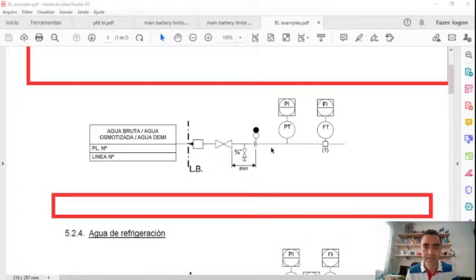Just to let you know, if you are talking about gases, and we need to reach 5 bar G at the battery limit, and for any reason the supplier is feeding 4.5 bar G, and we have a compression system, the compressor efficiency will be lower, and the gas delivered to the process will be lower, especially if we are talking about volumetric compressors.